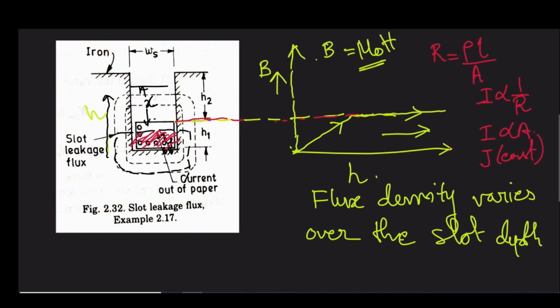This material's mu r is very small, so it is almost the resultant permeability, like here. So this is the case. Now the only change is that when you are increasing the amount of area, or the amount of current enclosed by your magnetic path, you are getting more H and therefore more B. But once you reach here, say By is equal to mu Hy. After that Hy remains constant, because if you move upward, you cannot get any more current carrying material. So this is the nature of the curve. I hope it's clear.